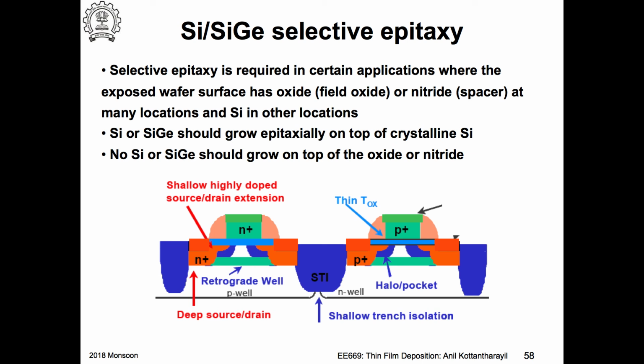But then, what would that silicon be? Amorphous, polycrystalline, meaning monocrystalline? It cannot be monocrystalline, right? Because it's growing on an oxide. Can it be amorphous? Yeah, but okay. We want to grow epitaxial silicon in this region.